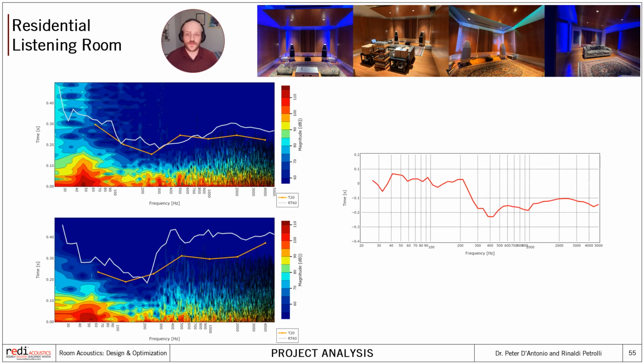And lastly, we have the full band temporal decay calculated from our combined simulation and the in-room measurements. Here, in addition, I've also included a prediction of the RT60 using a frequency domain technique, and up until 200 Hz, where we are using the wave-based method, the matching reverberation time is quite accurate. However, as we move into the mid and high frequency range, where we are using ray tracing, and we rely on the minimum phase transform techniques to generate the actual impulse response, we can observe a higher baseline of reverberation time due to the noise floor introduced by that minimum phase transformation, as I mentioned earlier when describing ray tracing.